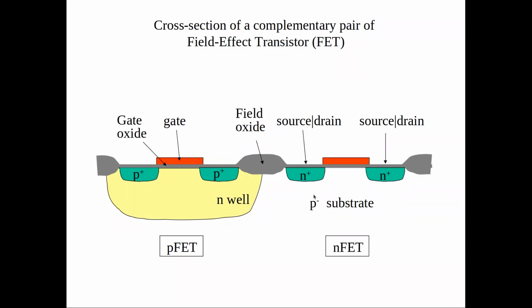But the other important part that you need is a very thin and well-controlled layer that is insulating, separating the semiconductor, which is your silicon, from your conductor. The conductor, in this case, is the gate, and it's implemented using polysilicon. Polysilicon is a highly doped semiconductor, so it's actually conducting, equivalent to metal. By having these p-n junctions and this very well-controlled thin oxide, you can really create this field effect transistor. And we'll see now how it works.